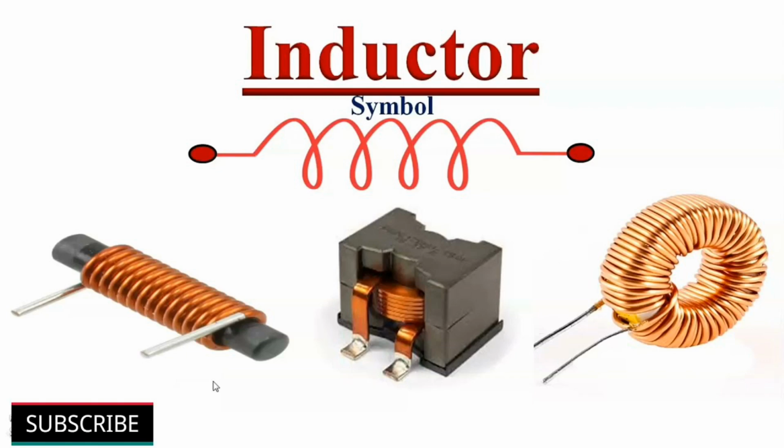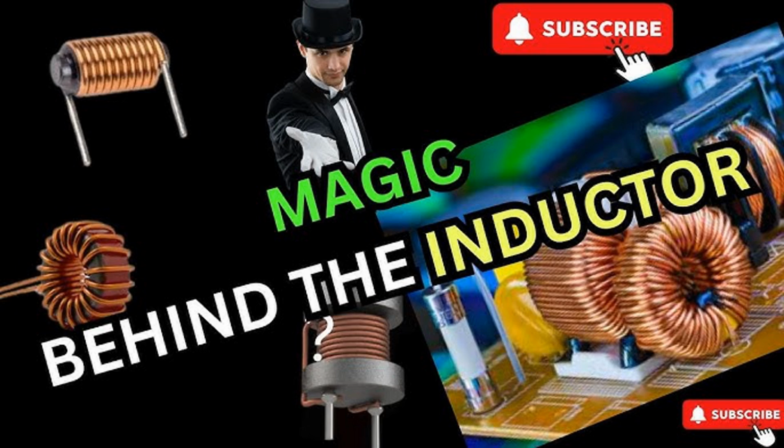Inductive proximity cards, RFID. Application: inductive sensing is used in RFID (radio frequency identification) systems, where an inductive coil in the reader interacts with a similar coil in the RFID tag to exchange data wirelessly. These systems are used for access control, inventory management, and contactless payments. Example: proximity cards used for access control in buildings employ inductive sensing to communicate with the card reader when brought close to it. Inductive sensing provides a non-contact, reliable, and robust solution for detecting metal objects, measuring positions, and enabling smart sensing in various industrial applications.